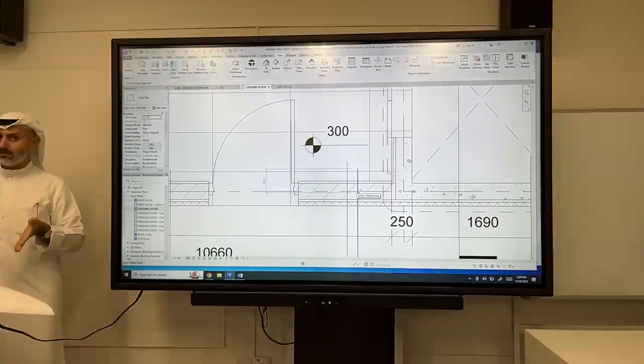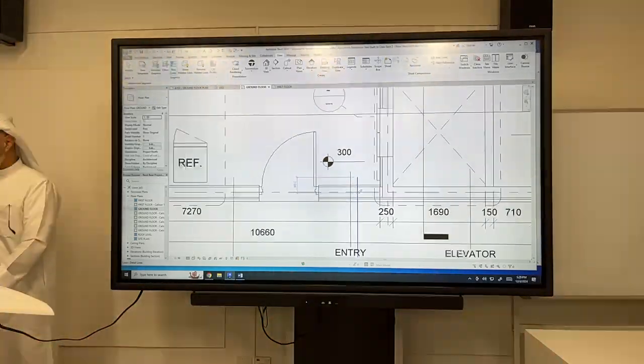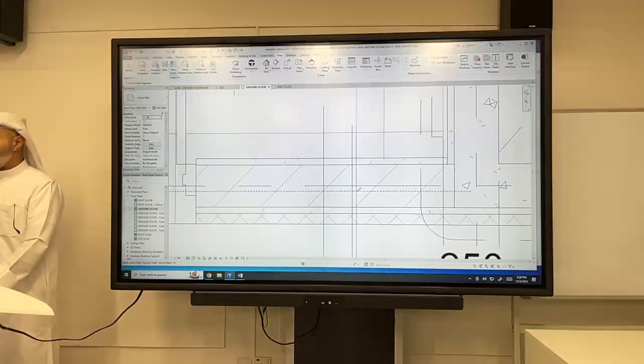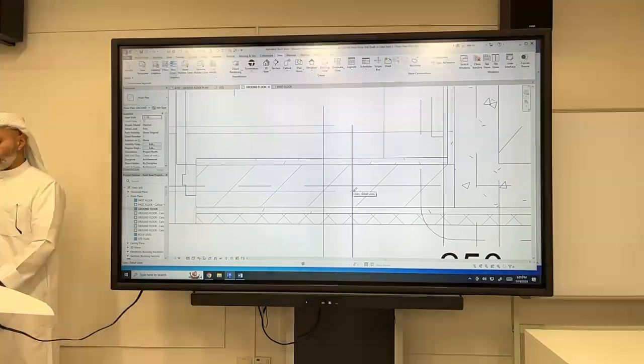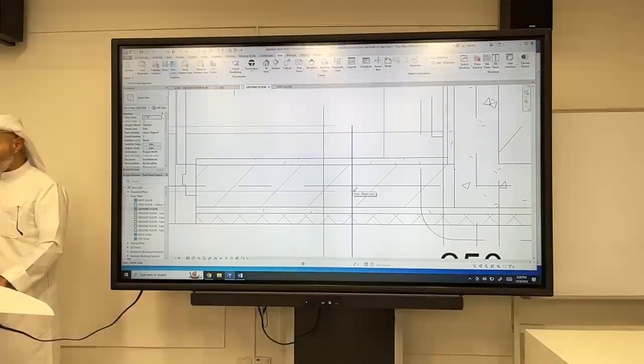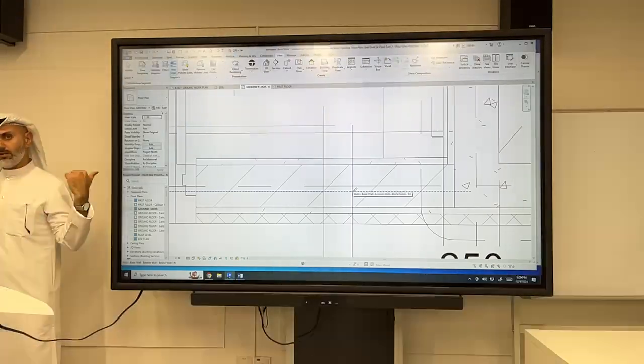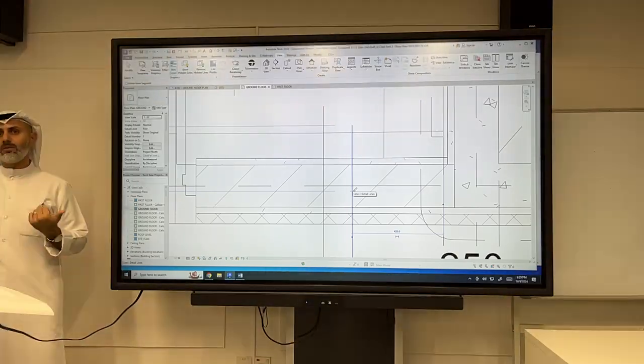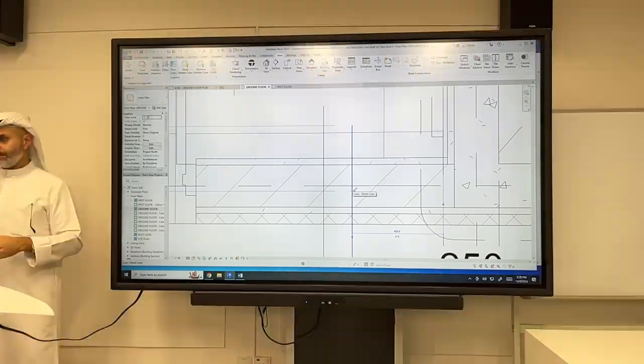It will select the line, and it's the highest one. So what I want to do is find the halfway line of the wall, this dashed line, and I just move the mouse to get to the line that I drew. Once you get to this line, you hit tab once, it will go back to the wall, and you click. This way you guarantee that you're cutting exactly where the detail line is.